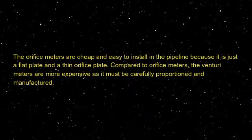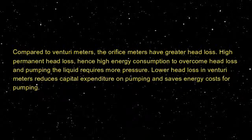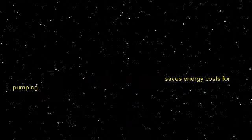The orifice meters are cheap and easy to install in the pipeline because it is just a flat, thin orifice plate. Compared to orifice meters, the venturi meters are more expensive as they must be carefully proportioned and manufactured. Second, compared to venturi meters, the orifice meters have greater head loss, high permanent head loss, hence high energy consumption to overcome head loss, and pumping the liquid requires more pressure. Lower head loss in venturi meters reduces capital expenditure on pumping and saves energy costs for pumping.